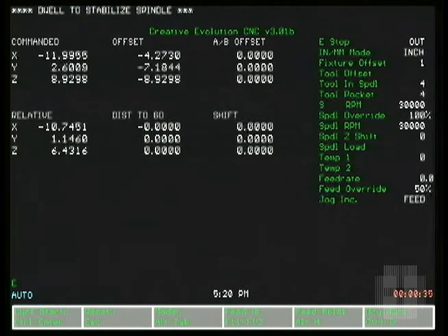Now let's restart our milling. The spindle will be started and the tool probed again. It can be especially important to allow some spindle warm-up in a case like this to normalize the spindle after any time sitting.